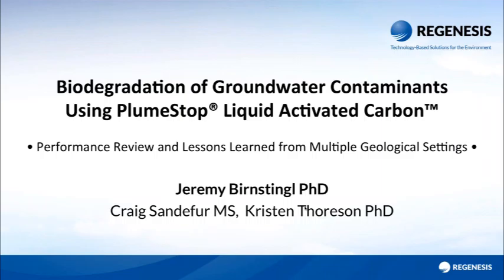Hairline fractures, granites, etc., I would look at these carefully because the material does remain particulate and you wouldn't want to block them. Chalk or dual porosity systems, again, we've not done any yet, but the movement should be pretty good. The capture of PlumeStop on these materials should be reasonably strong. They're not precluded, but they are things that we need to look at carefully, case by case.